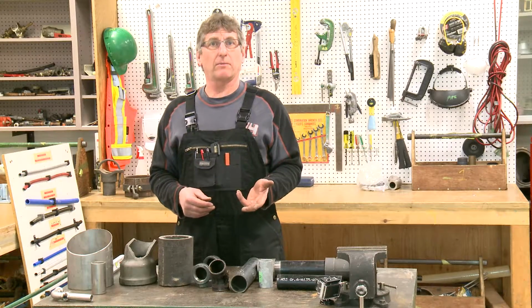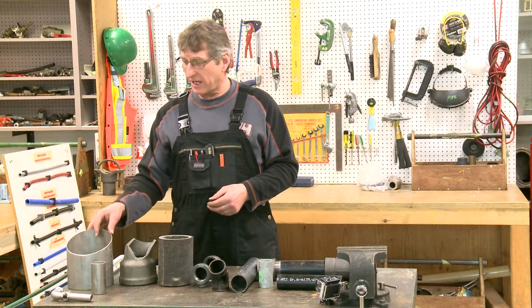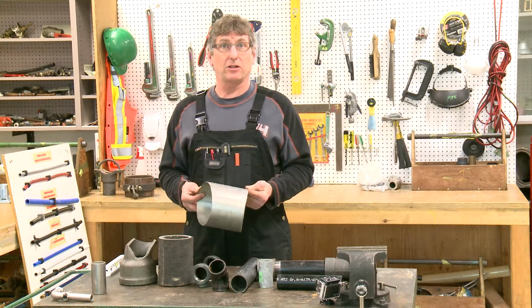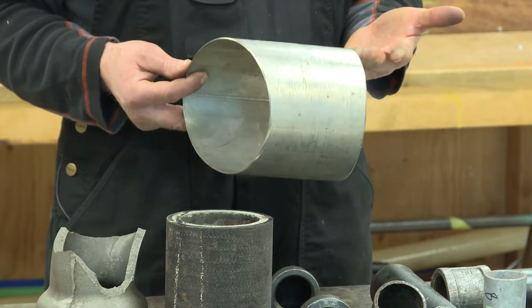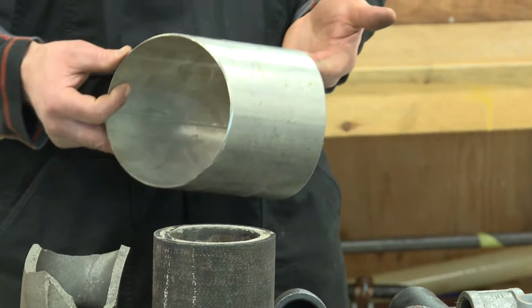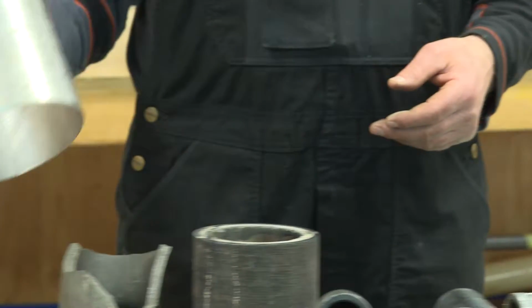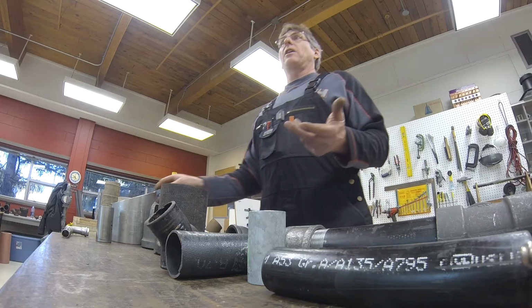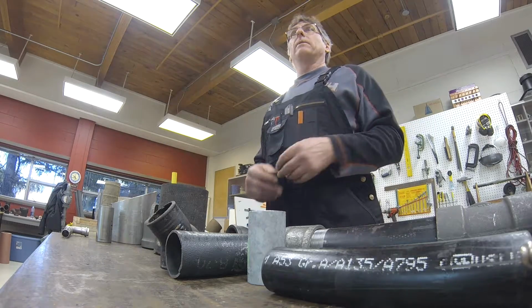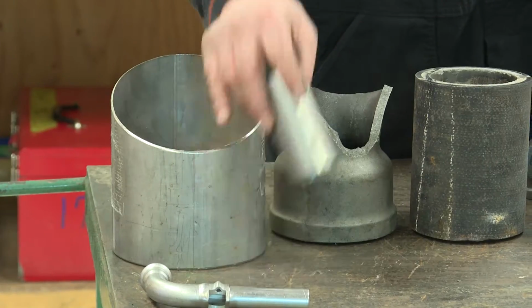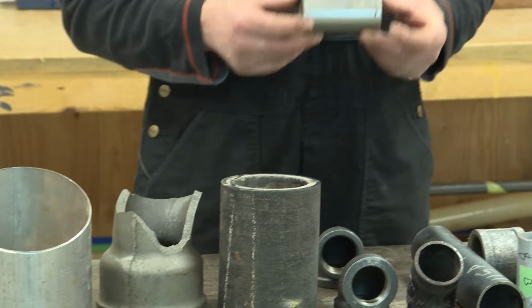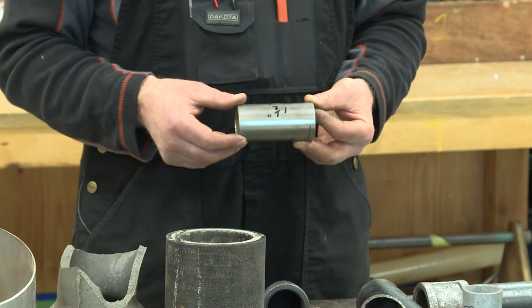Stainless steel is another metallic alloy. The elements added to steel to create stainless steel are chromium and nickel, which give it a high resistance to corrosion and heat. The amounts vary depending on the type of stainless steel. They range from 4% to 27% for chromium and 0 to 22% for nickel. The American Iron and Steel Institute has assigned series numbers for different grades of stainless steel.